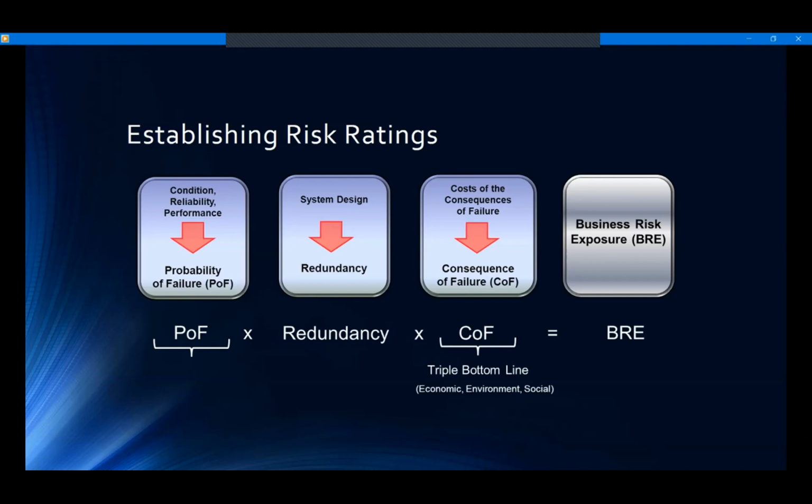Our condition ratings model incorporated 5 areas. First, a definition for our rating system, which is 1 through 5. 1 being excellent, 5 being failing. And then across those, we use that based on operations, maintenance levels, maintenance type, and useful life. Once we did that, we could complete our historical data to determine reliability and performance of our assets.